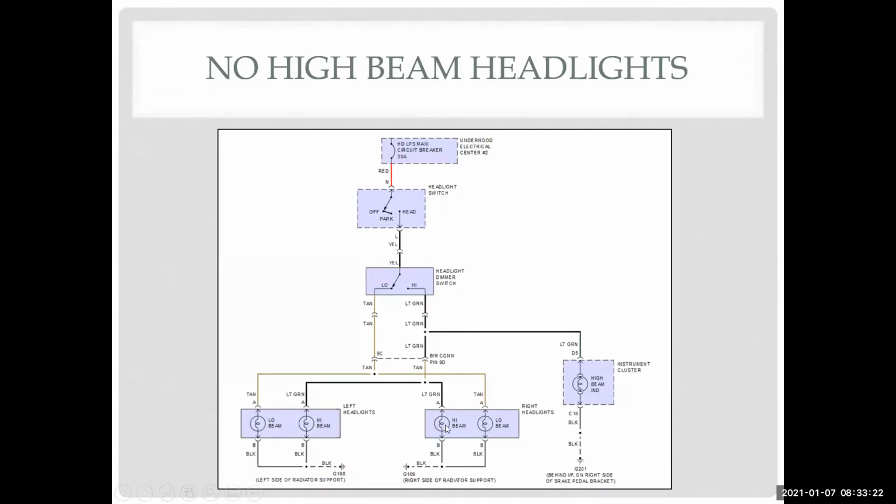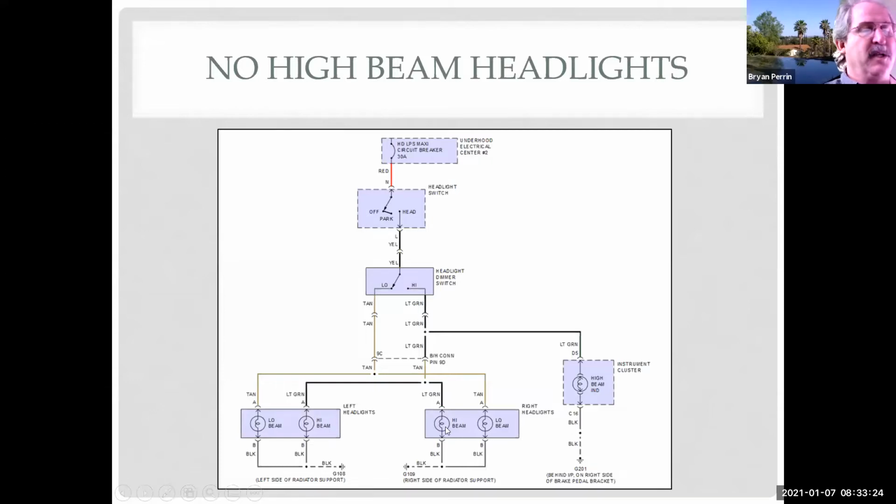So now it's what's easiest to get to? Well, if it's the light bulbs, I'm going to go there, aren't I? Because I can test for power very quickly or put another bulb in or something like that. But you see how we figured out what's wrong. We figured out what can't be bad through a process of elimination, which left us with very few things that could be bad.